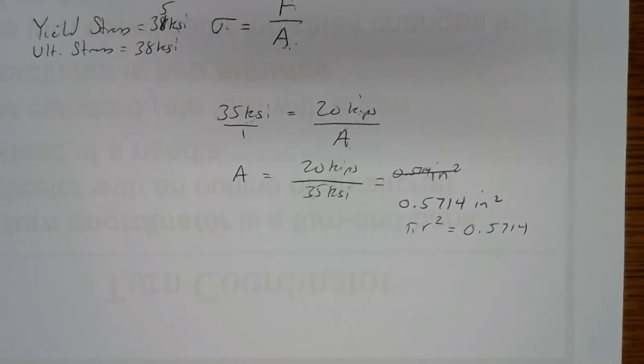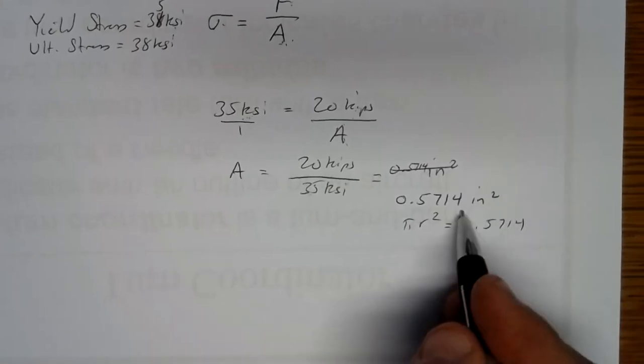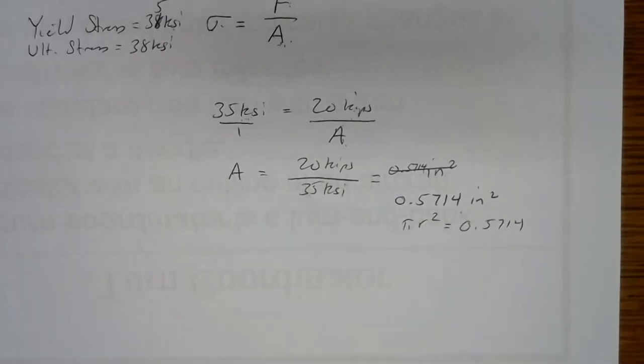Well, maybe 7/8 inch diameter rod is not really easily available, but I can get 1 inch. 1 inch would definitely work for us. I certainly wouldn't want to go down in area, but I'd want to go up. So as far as picking materials off the shelf to use, as long as it has the minimum amount of area, we won't be exceeding our yield stress.